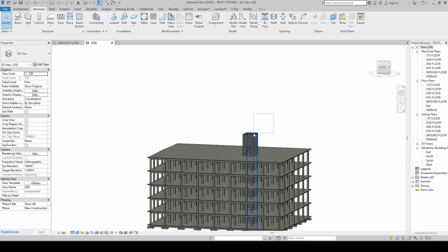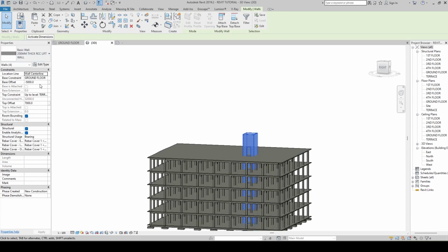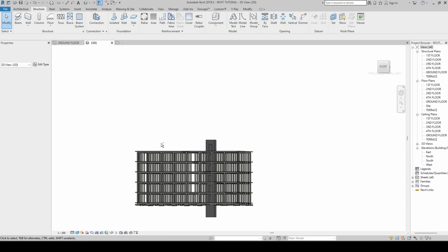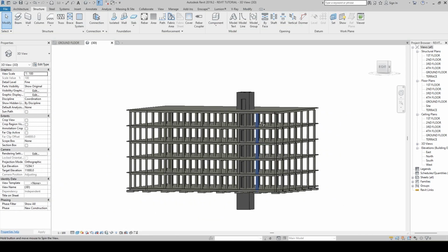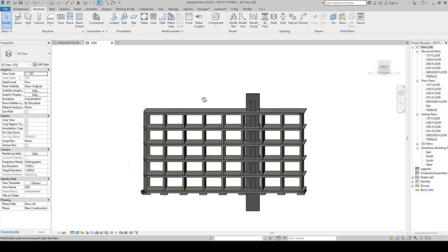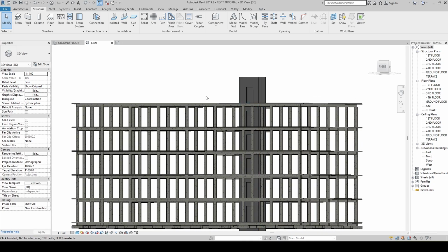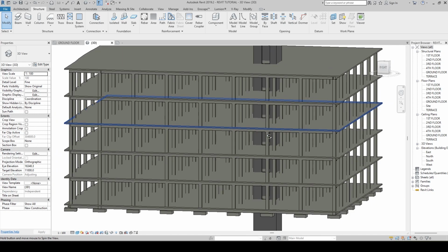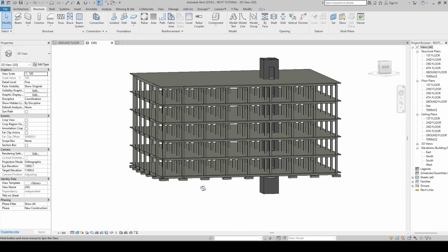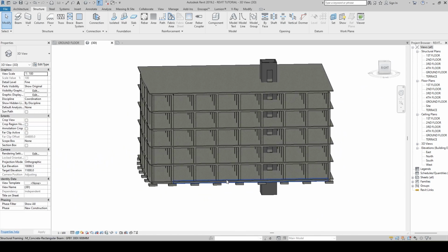So I'll reduce this much height, I don't need it. I reduce this base offset to maybe top is I add 7000, I think 5000 I'll make. It's fine, right? Now almost looks fine because headroom I have just taken as extra. So yeah, looks fine. Now basically we have created almost the structural elements here.